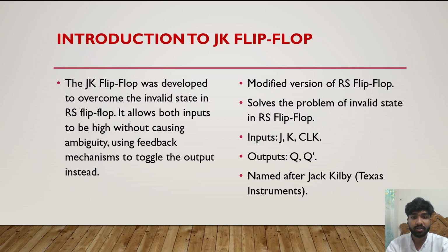Let's explore the JK flip-flop. The JK flip-flop was developed to overcome the invalid state in RS flip-flop. It allows both inputs to be high without causing ambiguity, using feedback mechanisms to toggle the output instead.